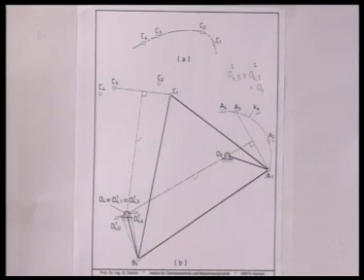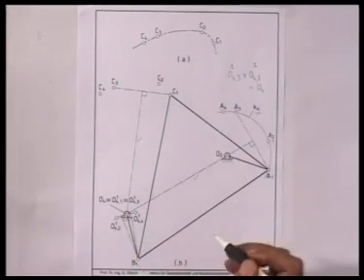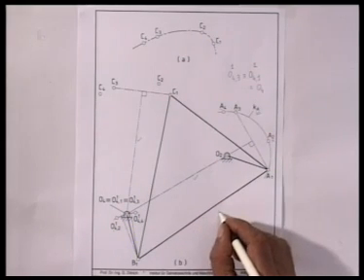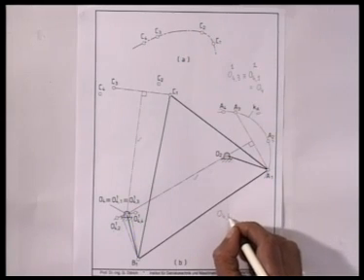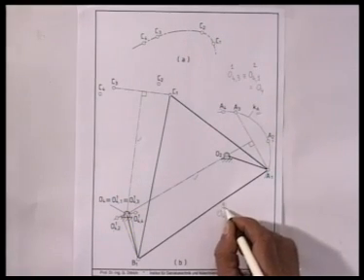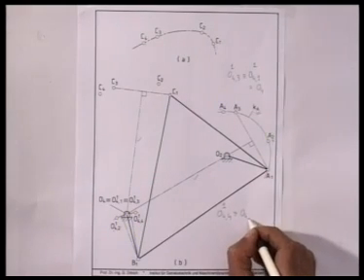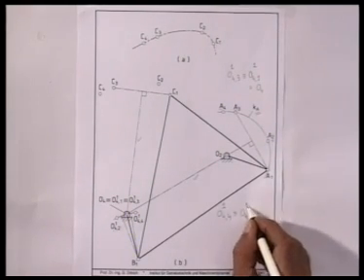As I said before, with reference to the function generation problem, I could have chosen different inverted positions of O4 to coincide. I could have inverted the whole thing such that O4 for the 4th position inverted on the first position coincides with O4,1,1.